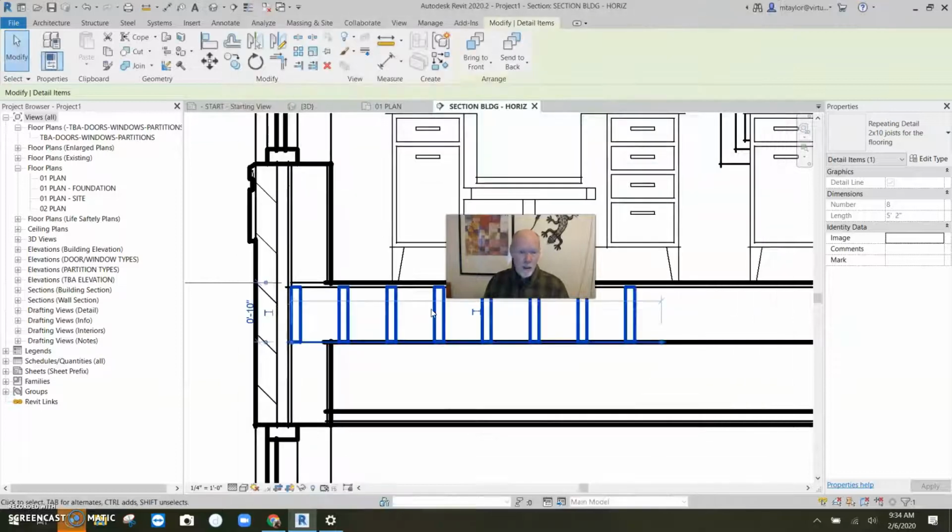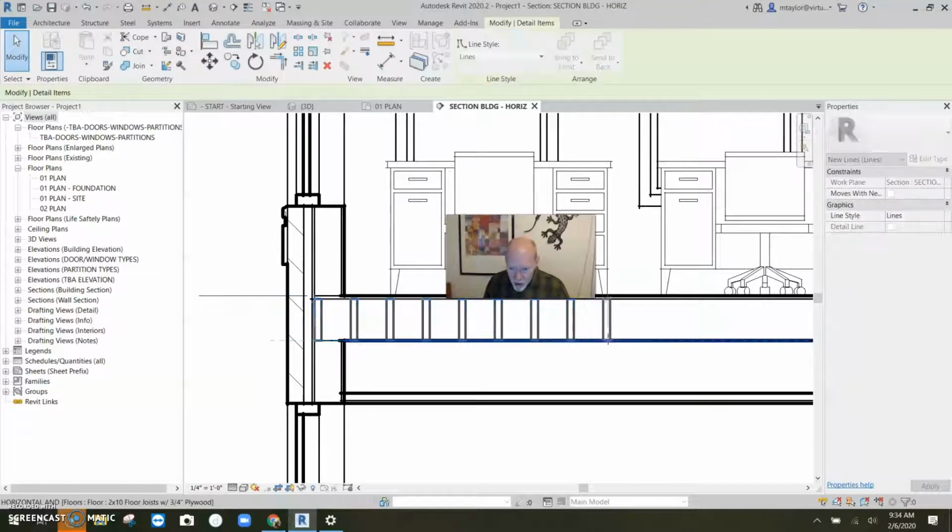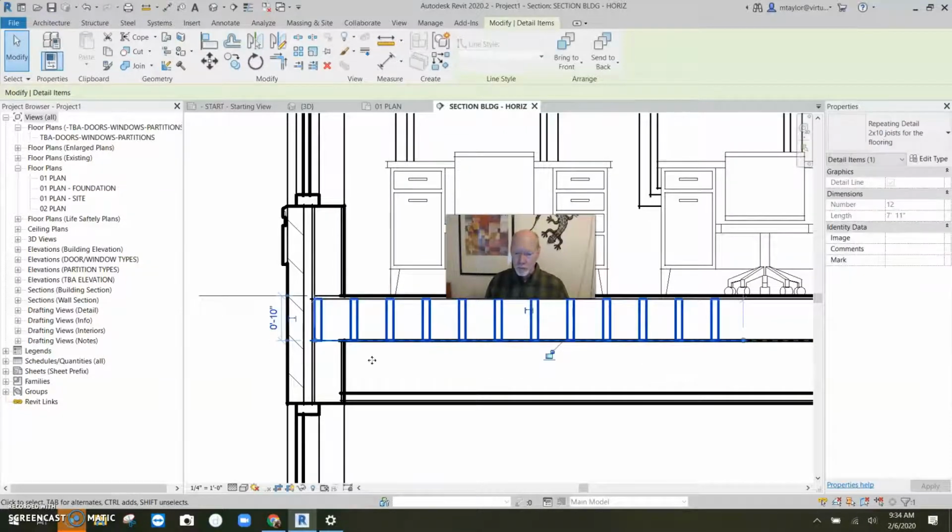And let's take a look at that. Oh my goodness, that's awesome. See those joists coming in? And all I got to do is pull this line. When it reaches that 8 inches that it's set at, every 8 inches, it'll place one, okay?